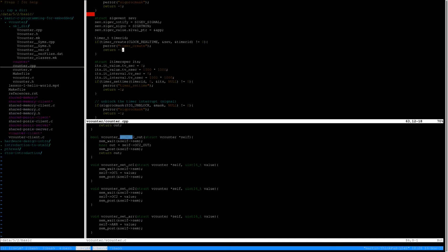So I've created the timer, but I haven't set the time for this timer. So the timer is created, but it doesn't know when it's supposed to fire. So now we have to configure the time for this timer. So I create an interval timer configuration here, and I set first the initial expiration, and then I set the interval expiration so that the timer will be reloaded, and it will then fire at this given interval. So first it will expire